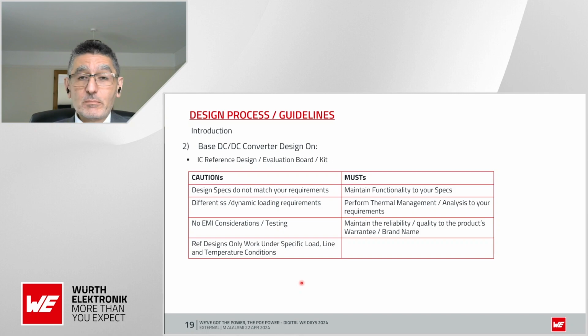So design specs may not match your design requirements. The reference design is not necessarily set to fit precisely what your requirements are. Usually you don't have any EMI rejection or filtering on those reference designs or eval boards. The reference designs also do not necessarily look at a wide range of input voltage and loading conditions. So you'll need to adapt the reference design, in simple words, to your design requirements and make sure that both steady state and dynamic performance is maintained for your requirements. That's one of the key aspects that you need to identify.